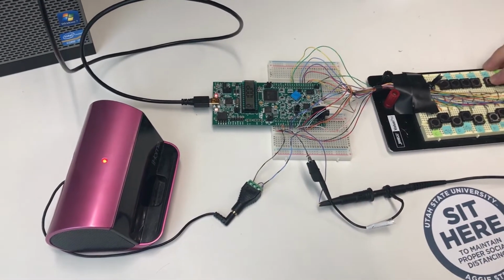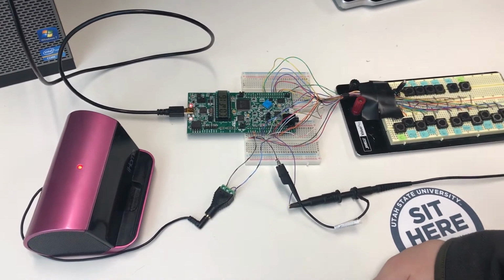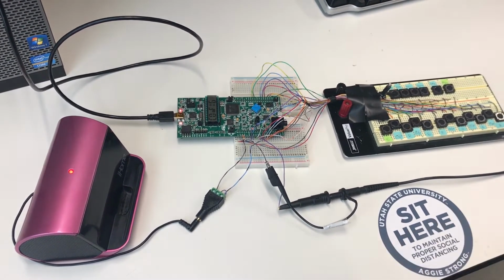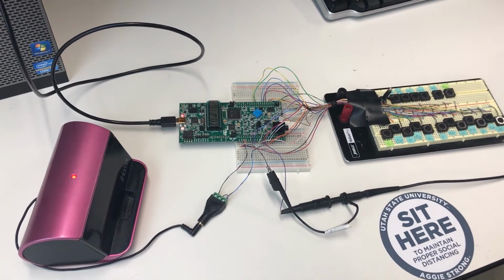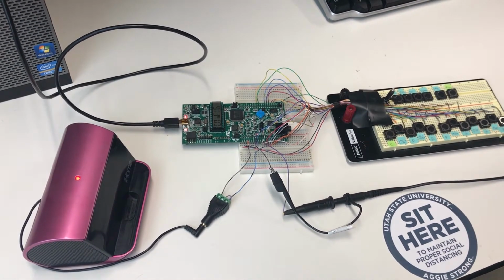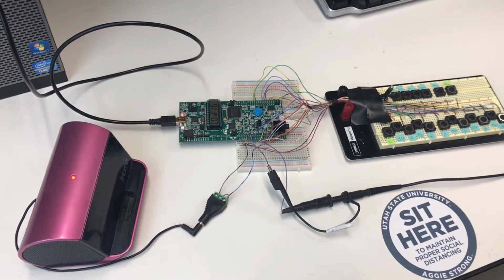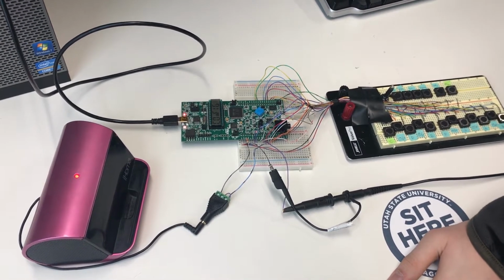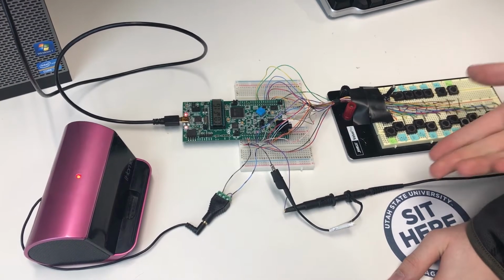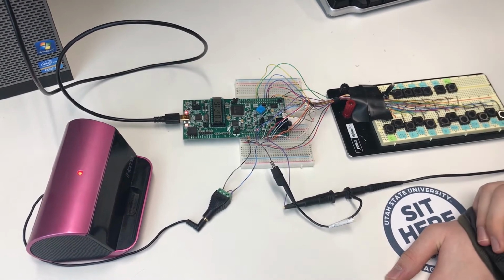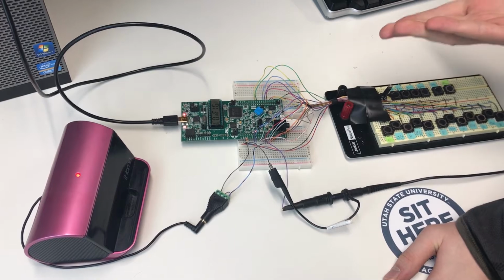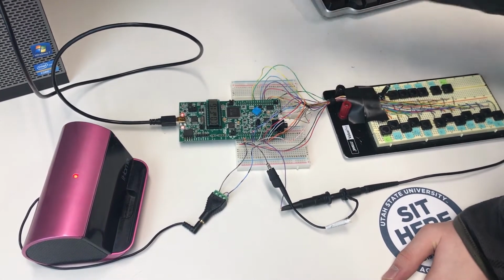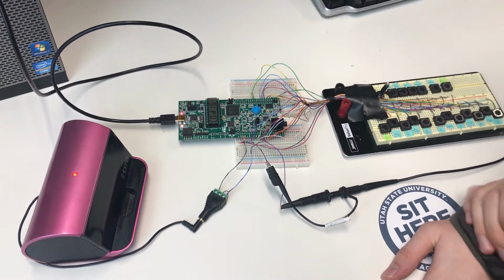Now I'd like to talk about how we are outputting the audio. As you can see, the microcontroller has an audio jack built on the board. This audio jack is controlled by a separate controller on the board. The microcontroller talks to that through I2C via the serial audio interface. The serial audio interface uses direct memory access. It was our original plan to use that serial audio interface in order to interface with this audio jack.